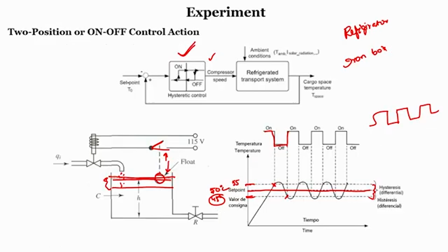So, when we recall, one threshold is 15.027 and the other threshold is 14.973. Since it is an inverting type of Schmitt trigger, if the input value is greater than 15.027, the output will be on, right, and when the input is lower than 14.973, the output will be off, reverse to this value.